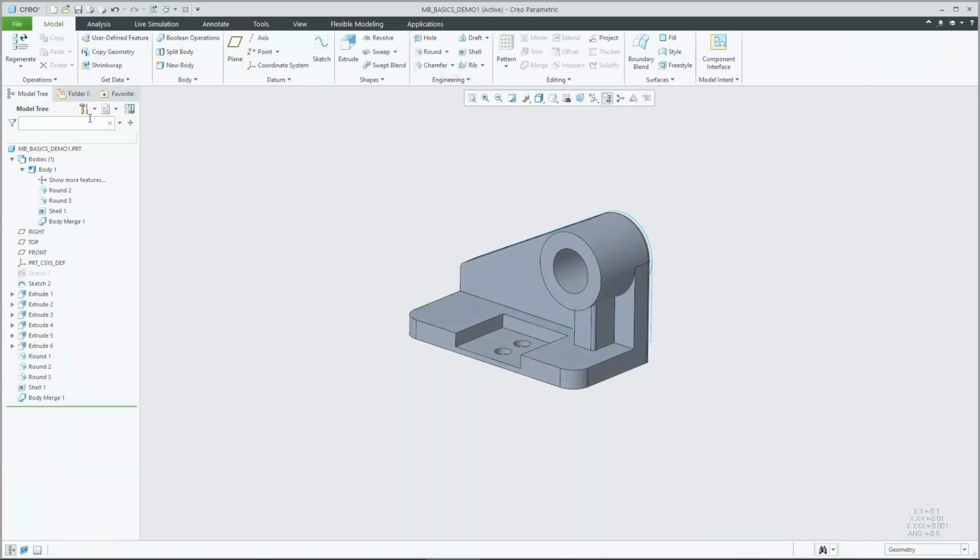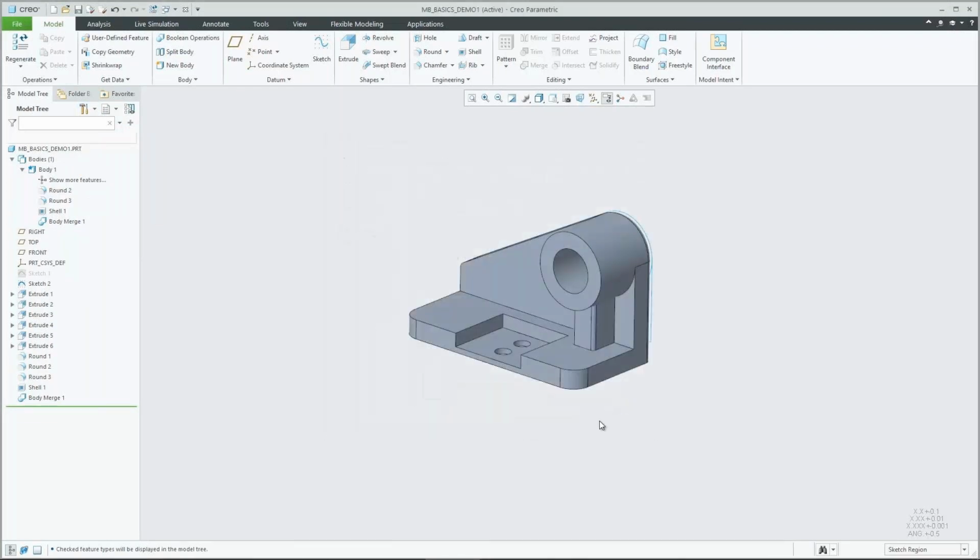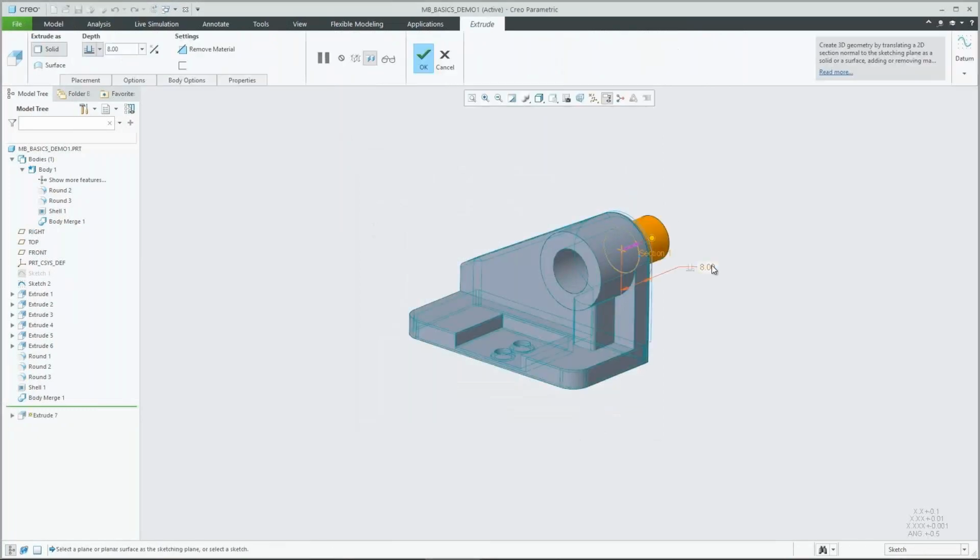You can merge them, so you'll see this is all now part of body one. So maybe you don't want two bodies going into manufacturing. Maybe you just wanted to use it because you want a shell. You can very easily, okay, great, you have a design, split it into two bodies, do something to one of the bodies that you don't want done to the other, and then merge them back together. That results in still only one body, but it made it very easy to do that feature change or that edit.